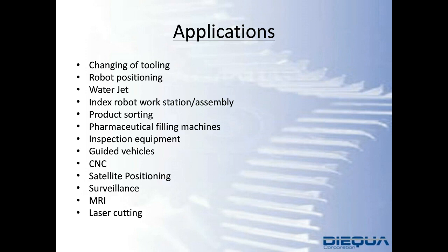That's where having a very high precision, angularly stable connection would far exceed a hollow keyed, hollow shrink disc, or a solid shaft. Inspection equipment, high repeatability. They don't want an influenced reducer to give you additional backlash, additional play that then will alter or change the results.